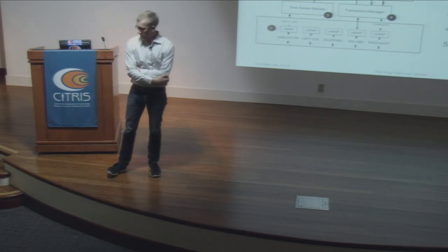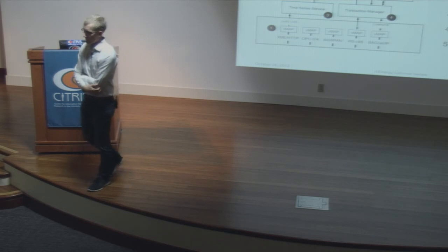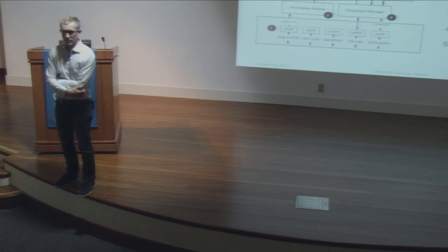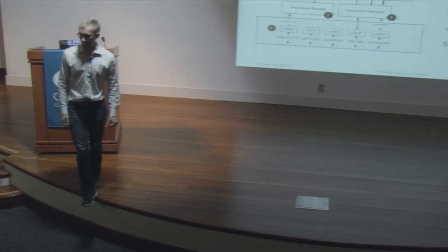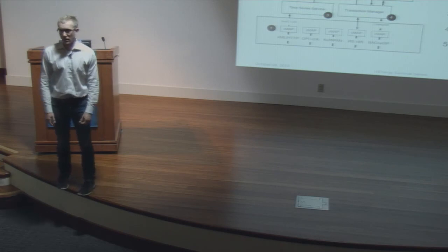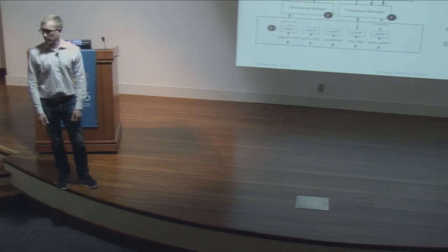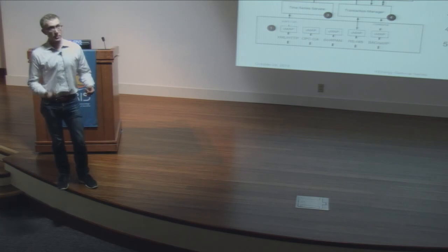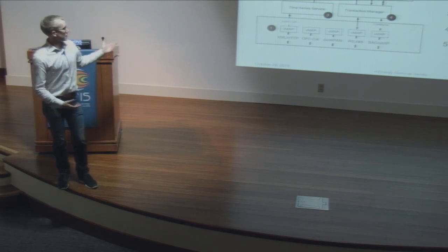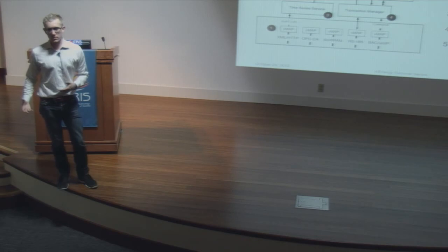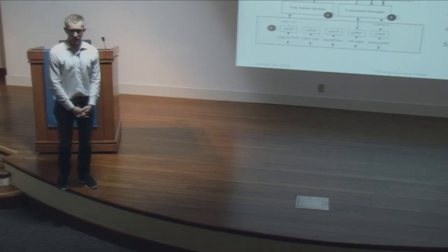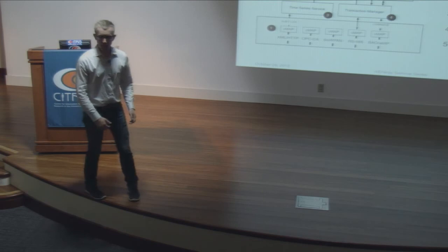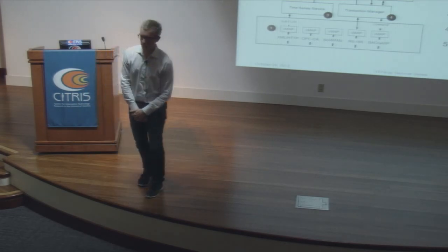I think in that particular one, they more or less hardwired the set of outputs from sMAP into EnergyPlus, and then the set of outputs from EnergyPlus. So they really didn't have an epistemology or anything that would capture the relationship. Right, yeah, and that's similar to what we did in this building for the BLAST kind of thing. The real goal of this is to enable portable applications, so that your MPC controller or your BLAST could run in many buildings that look superficially similar, VAV buildings, stuff like that. Any other questions?